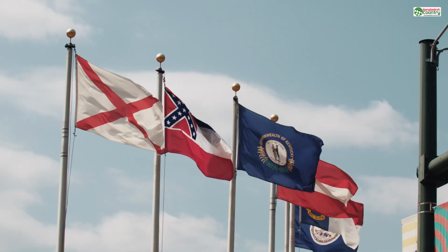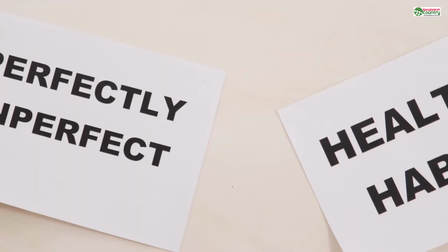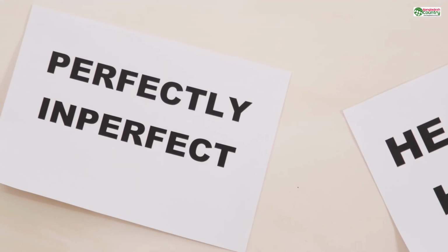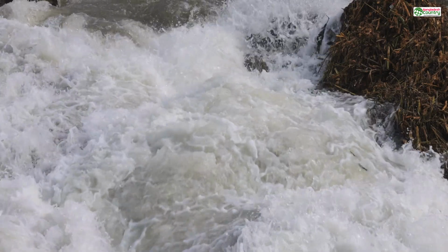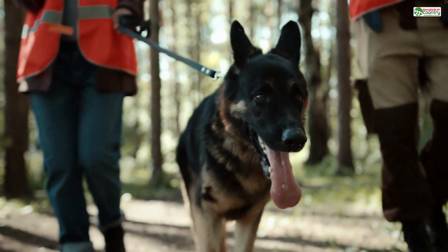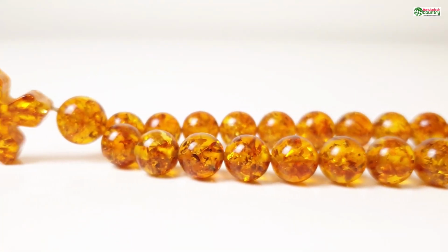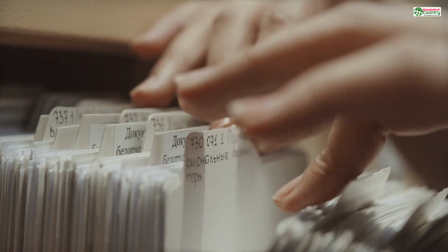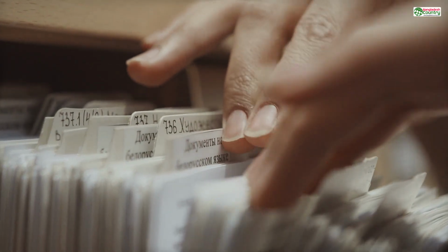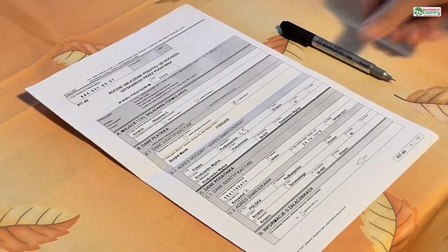This state is called non-manifold geometry, which is just a fancy $20 term for leaky. The software tries its best to guess, but its guesses are often catastrophic, leading to missing walls, bizarre internal structures, or just that stringy spaghetti mess we all dread. Your file must be a single, continuous, sealed surface with no holes. It has to be completely watertight.